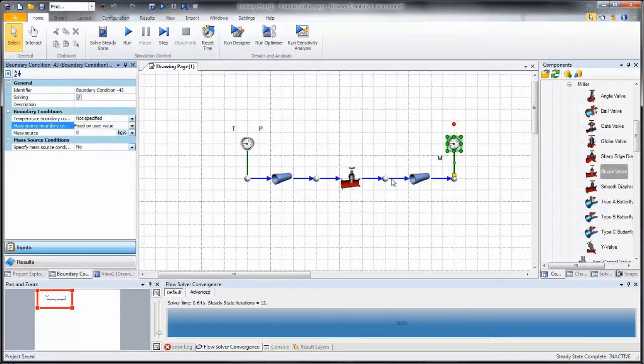A source, on the other hand, is something that is generated or lost at a certain point in the network. So if we want to have a mass flow of, say, 10 through the system, then we need to tell Flownex to discard or release that quantity into the part of the system we are not modeling. So the generated value will be minus 10.